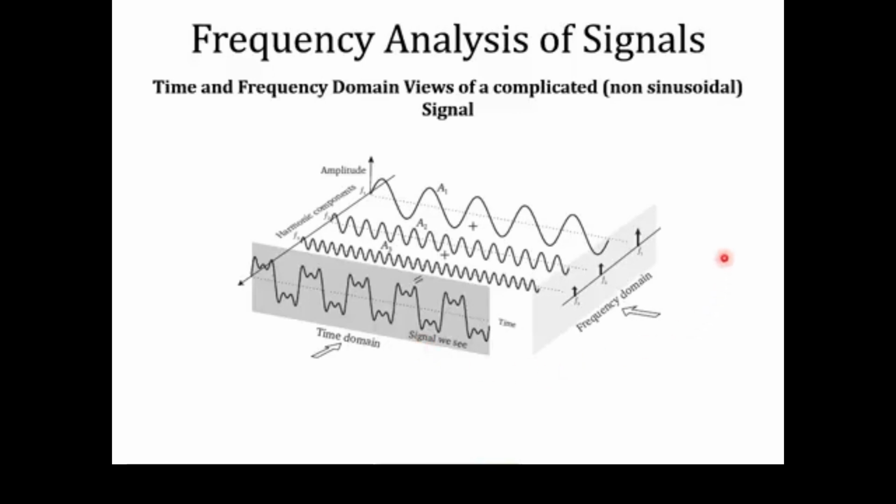So suppose if this is the spectrum of our input signal which we have applied at the input of some filter, which contains three components f1, f2 and f3, and let's assume we have also calculated the spectrum of our output signal which contains only one spike at f1 hertz, and the output spectrum doesn't contain these two spikes. So we can simply conclude system characteristics like our system is designed to reject these range of frequency values.